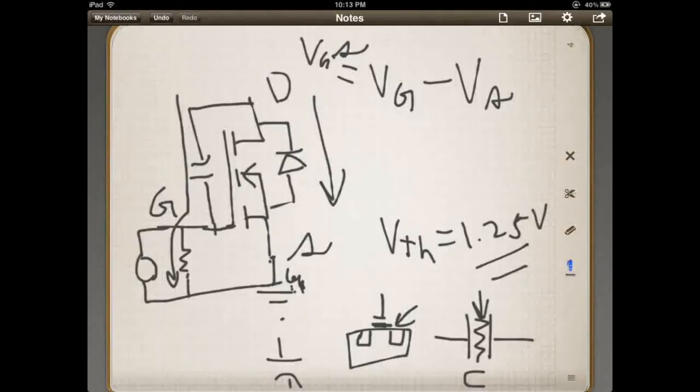But this one, you definitely got to bleed to ground through something, especially if your voltage is like a relay or something where it just completely opens. There's no physical tie at all to get this to ground to bleed that off. So that's where also your timing comes in. There's an RC constant there then. So you've got some RC constant, okay, that equals your time.